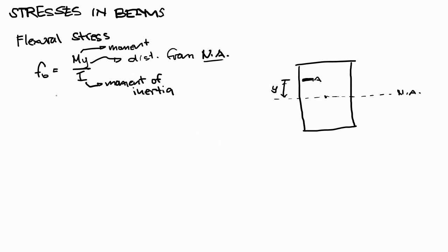Okay? Now, if you observe, relatively constant yung moment of inertia sa isang section, yung I that is based on the shape, yung y lang nag-change dito. Depende kung saang point yung kinukuhanan mo ng flexural stress. And if you put yung y mo sa pinakamalayo na lugar, or we call it the most extreme fiber, either in the top or the bottom, we label it as letter C, at yung makukuha mong flexural stress dyan would be the maximum.